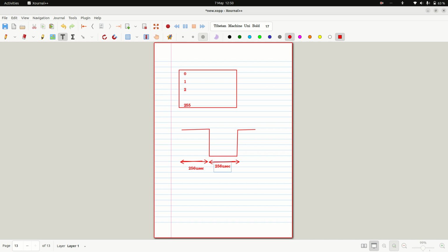So here the same thing happens. You need to preload the value. So in the ISR toggling happens. Now I have to make sure to reach the ISR in just 4 microseconds instead of 256 microseconds. So we need to preload the value to the timer register. So what do you think we should start with? So 252, is it possible? After 4 counts it reaches 256, isn't it?